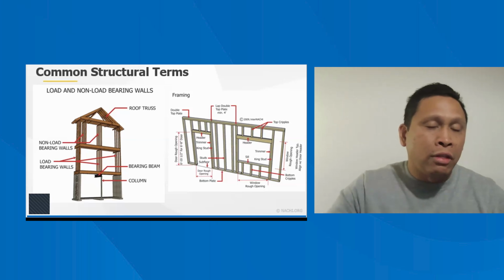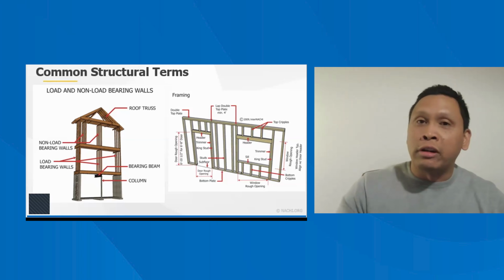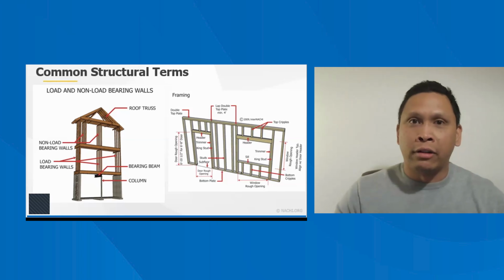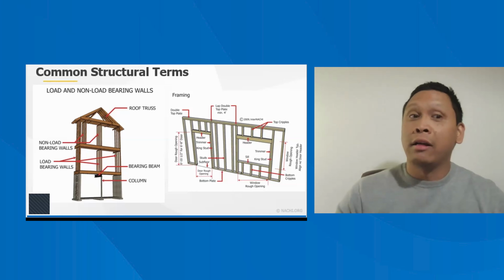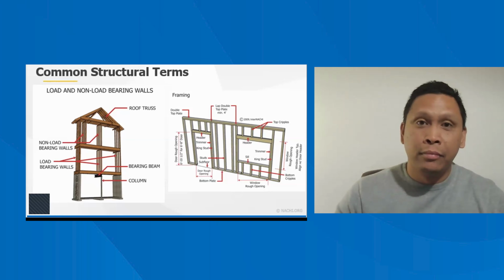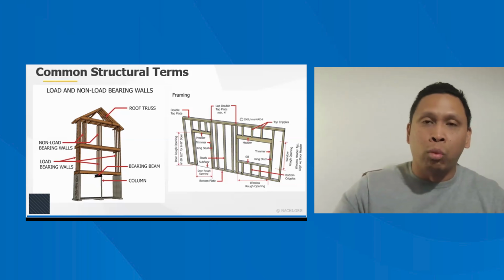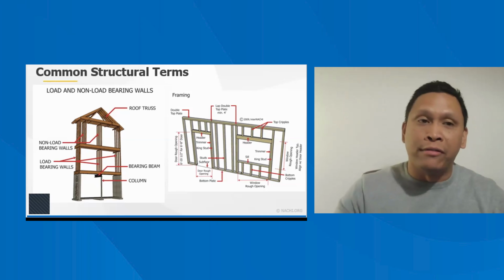And now I'm also noticing that the floor has a low spot here. Now you're starting to connect the dots. Crack on the foundation, window hard to open, I've got a floor that's starting to get lower. This might actually be a structural concern. So it's not just one condition or one defect.